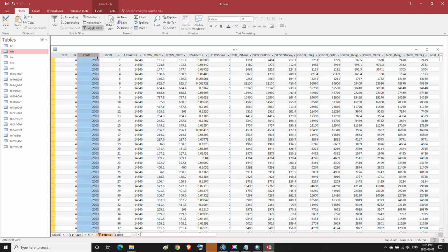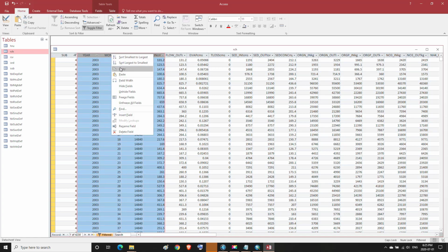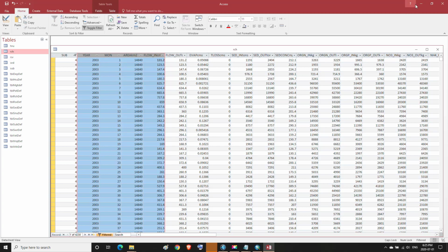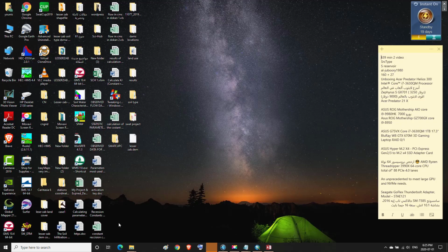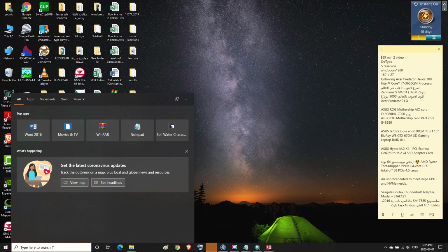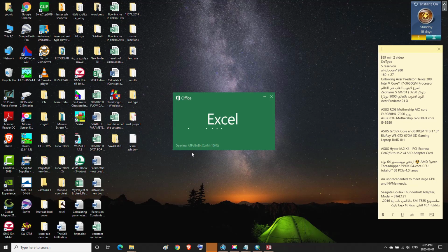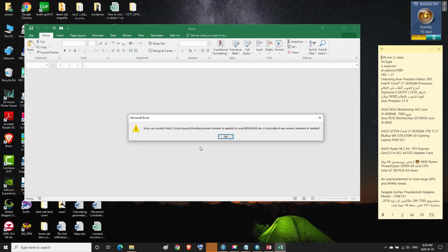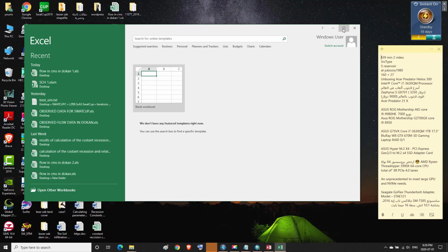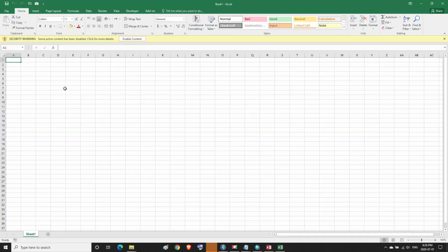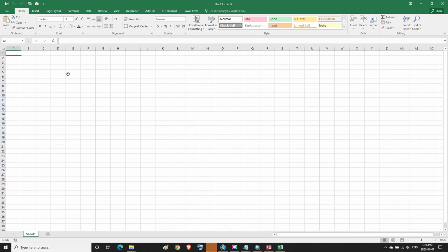We select and activate the year, MON, area, and flow-in fields, and we copy them. Then we open the Excel program and paste these daily discharges, as we see.